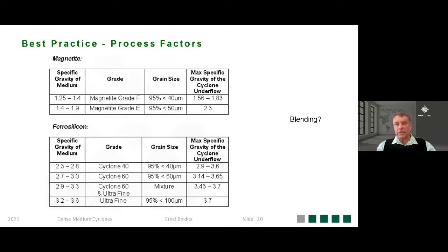Progressively, your magnetite is at the back end of being recovered. So if that starts to happen, you start to lose progressively more magnetite out of the process. Now your ratio of magnetite to ferrosilicon has changed, and you need to be aware of that. And that comes back to being able to determine differentials, because if you measure your differentials and you know what you're looking for, you can detect those deviations and take corrective actions timeously.